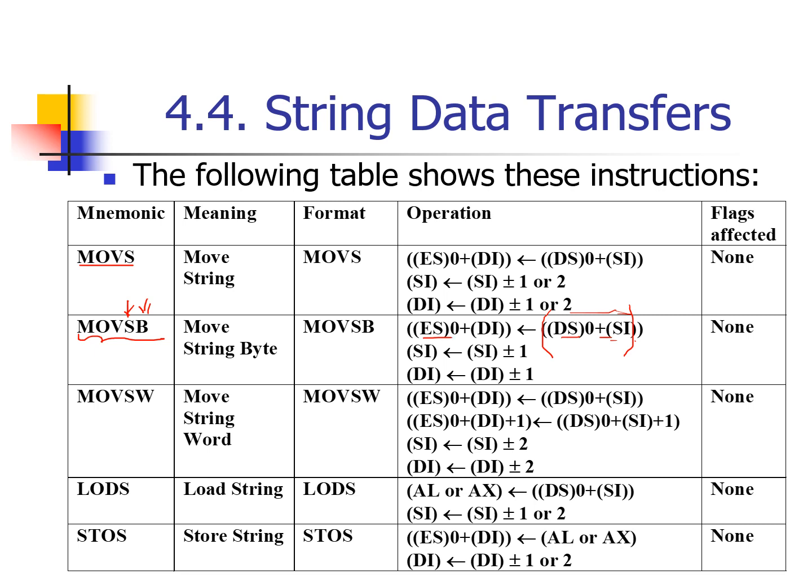This memory location is determined physically by multiplying the value of ES by 10, adding the content of DI to it, and we get a memory location. So you are moving an element of data from DS at this specific location to ES at this specific location. And if you are moving byte by byte forward or backward, you have to increment your SI and DI by 1.